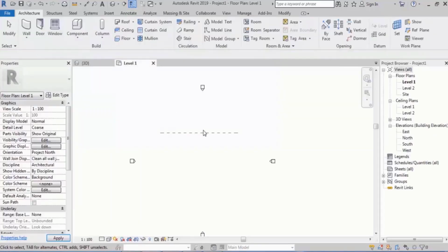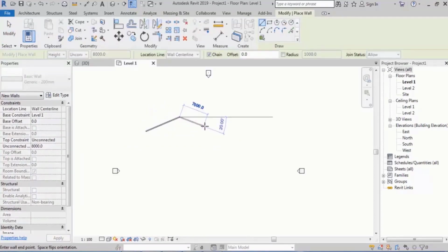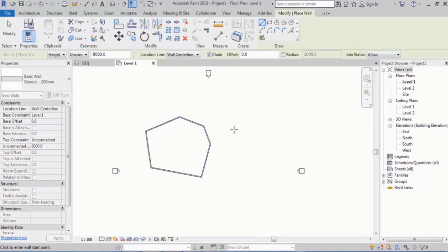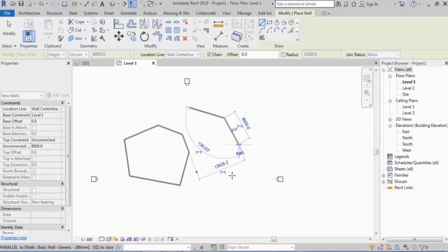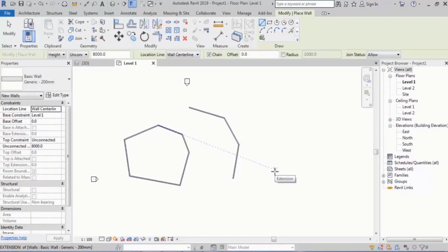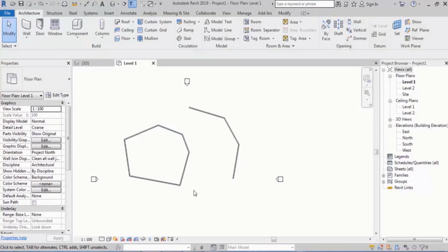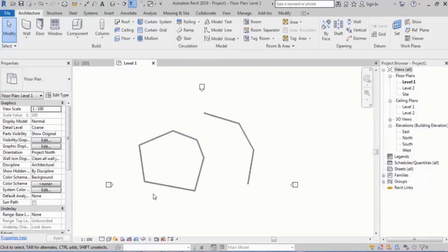So now I go to the environment of the project, pick a wall. As you see, I draw it. In that environment, I used line. Here I use wall. Now, answer my question. If we are about to select all of these walls together in this environment, except opening a box, what should we do? That's right, we need to hold our mouse on one of them, tap, and then click.